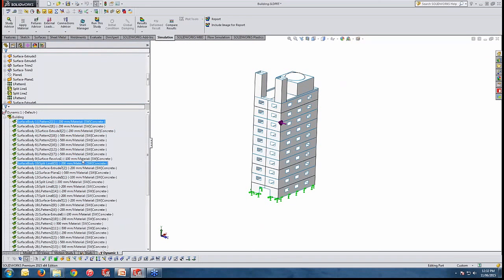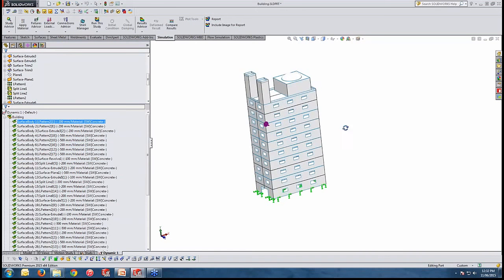That is all defined, but again, if you take surface CAD geometry, it is converted automatically. It is very important that such a simplification makes the model meaningful to your FEA study, rather than having a very detailed representation and spending a lot of time on unnecessary calculations.